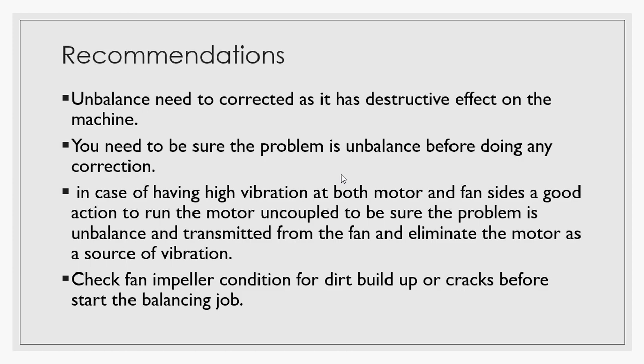To be able to decide if the problem is from the fan or the motor, and to be sure it's not residual imbalance in the fan transmitted to the motor, decouple and run the motor by itself as a solo run. If the vibration levels exist, you can be sure it's from the motor. If not, it might be from the fan. And anyway, if you want to correct it without sending the motor to the workshop for balancing, you can balance the whole system from the fan side, or from the impeller side of the fan.